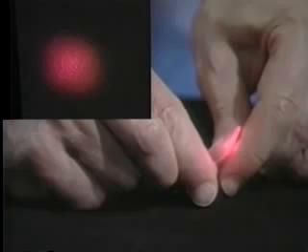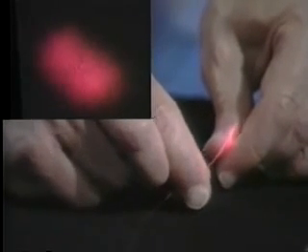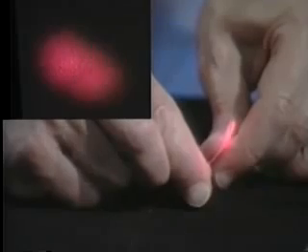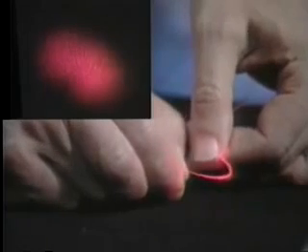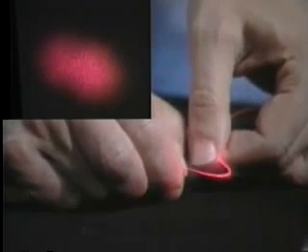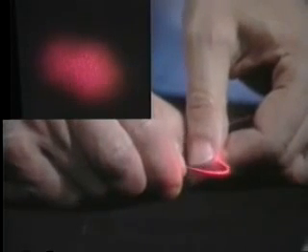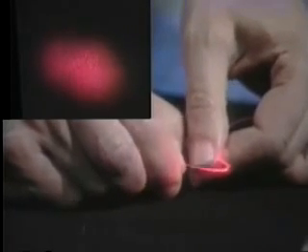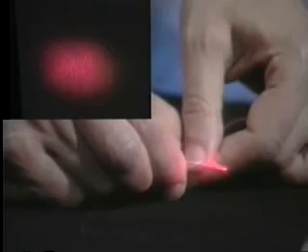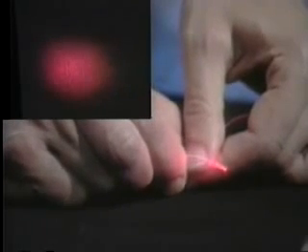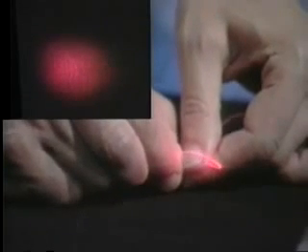So here we have single mode propagation, and here we have multi-mode or a mixture of multi-modes that are propagating in the fiber. Again, you can see that there's a lot of light that gets kicked out of the fiber. You can see the bend absolutely glows. In fact, this bending effect on the transmission of light in a fiber can be used as a sensor. A sensor of pressure, sensor of stress, bends, and what have you.